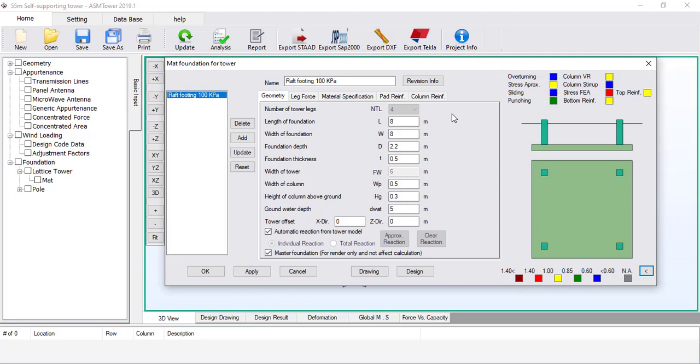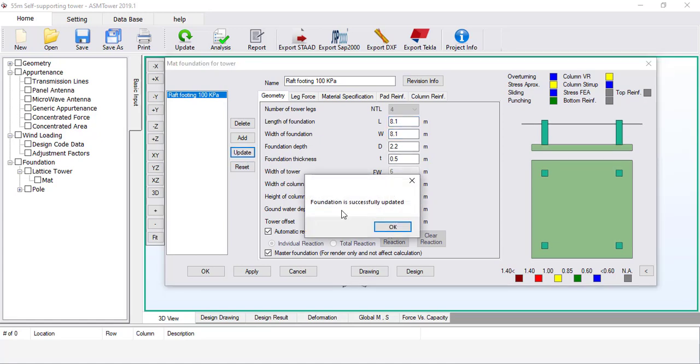The second stress is the exact stress that is calculated using the finite element analysis. Finite element analysis can handle flexible or rigid foundations. In this example, the first pressure assuming the rigidity of the foundations is greater than the second stress resulting from finite element analysis. Stress index color of finite element is red. That means unsafe. Try to increase the dimensions of the foundations to 8.1 meters. Click Update. Click Design.